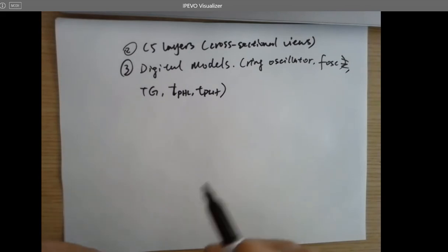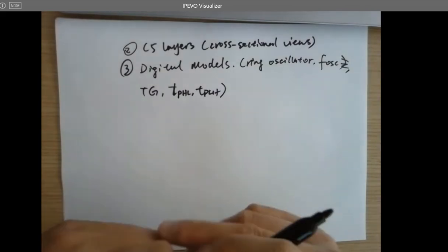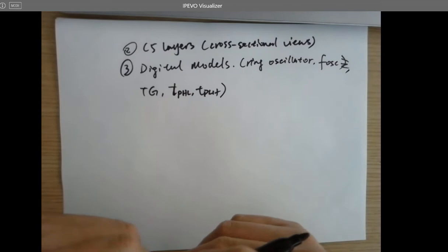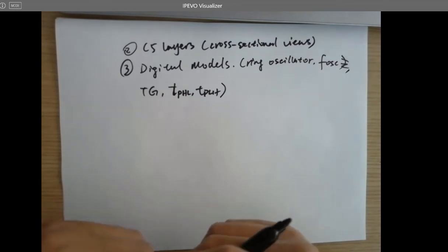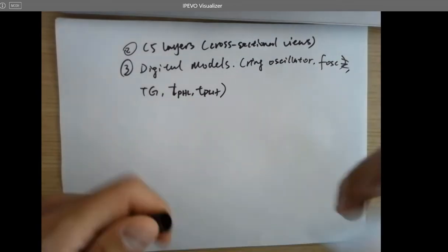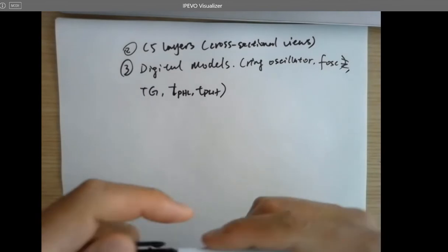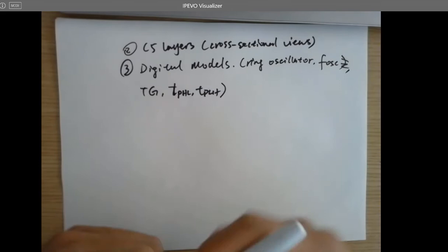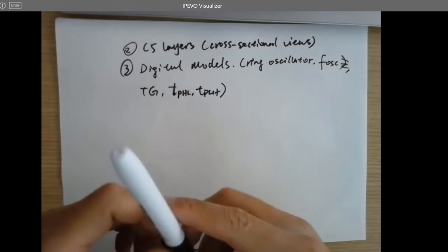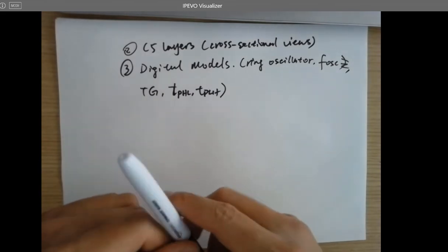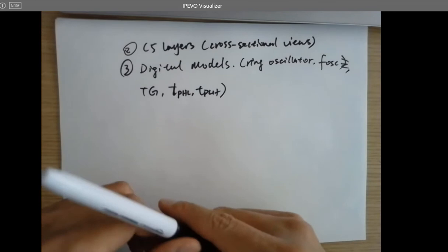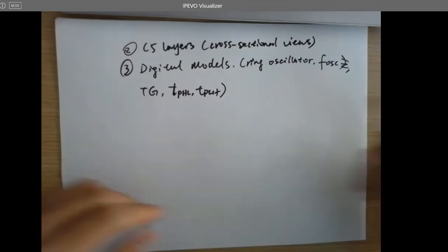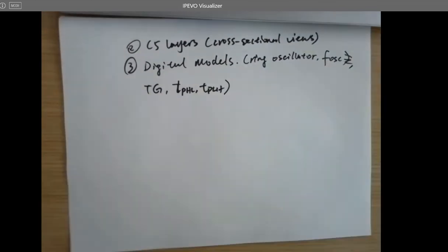So, for example, I tell you I need at least 500 megahertz, and eventually you calculate it and find out you need probably 5.4 inverters. Have to think about, do you want to pick up 5 or 6? So if you have more inverters, are you going to have a faster oscillation or slower oscillation, and why?